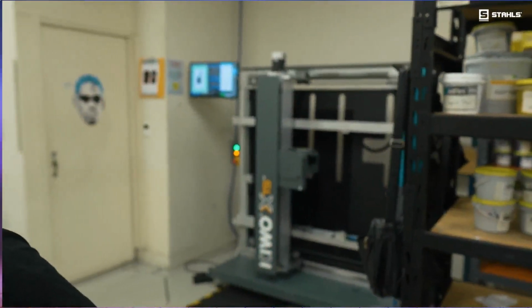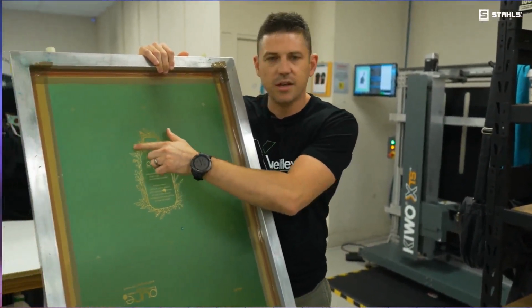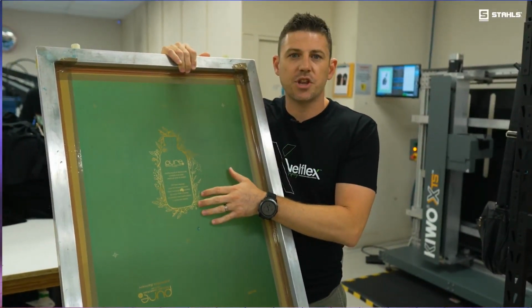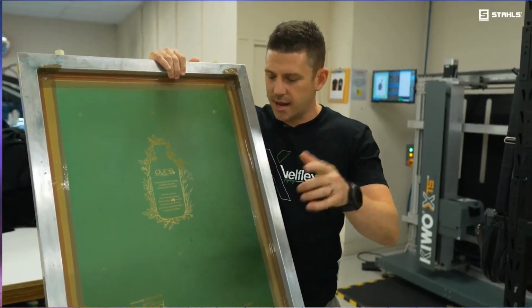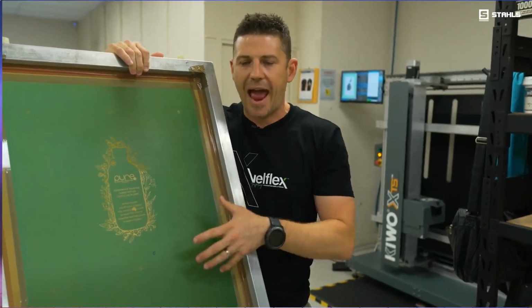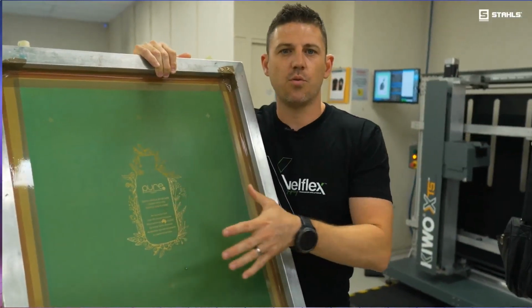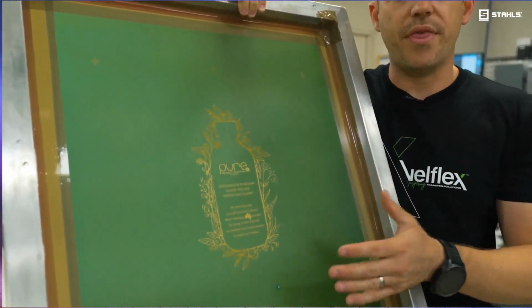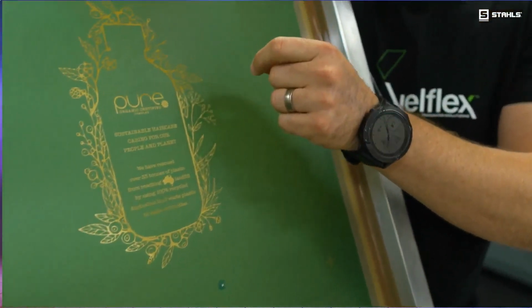And what you're left with is a screen here that has a stencil in it of just clean mesh that allows the ink to print through, okay? And that's what you saw Callum doing earlier. This here is called emulsion, okay? And this is a UV activated emulsion. So obviously when you print the image on, we harden the emulsion, we're then able to wash out the print, and it leaves you just that mesh right there.